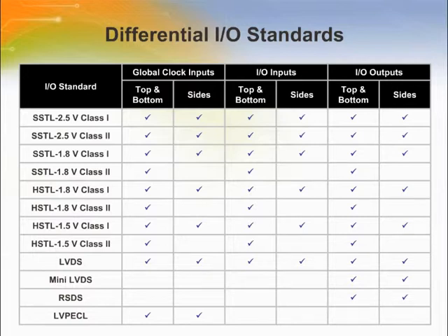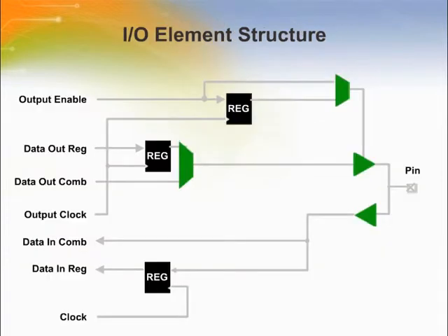From high-speed backplane applications to high-end switch boxes, low-voltage differential signaling (LVDS) is the technology of choice. LVDS is a low-voltage differential signaling standard, allowing higher noise immunity than single-ended I/O technologies. Its low-voltage swing allows for high-speed data rate transfers, low power consumption, and reduced electromagnetic interference.